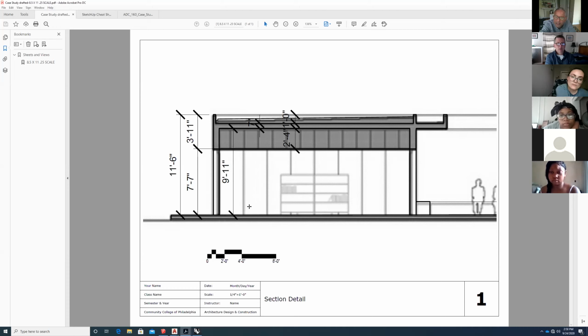And then I accidentally pulled it up too far. It really should have only been 2 foot 4 inches thick. That's the distance from here to here, 2 foot 4. And then we're going to come back later and I'm going to do the roof slab that's 7 inches thick. And then we'll be almost done with most of the architecture of this building. Okay, but I'd like to take a little break now. But if there are any other questions, I'd be glad to answer them.